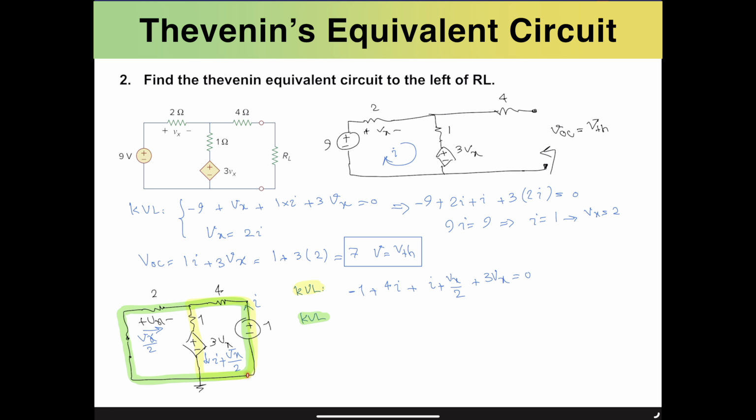path. So essentially, starting again from this bottom and moving up through this resistor, through this voltage source, that would be again -1 plus 4i. Then we hit this point, which we have minus Vx, and then we get to the ground. Minus Vx equals 0. So that will be our second equation that we need to consider.